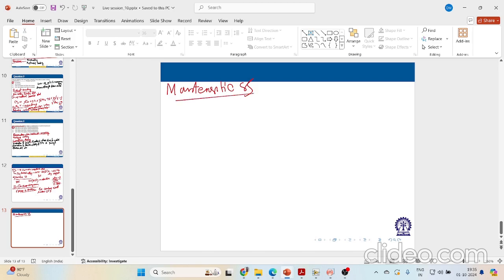Now, martensitic stainless steel can be said to behave like iron chromium alloys containing less than 12% chromium. If it is containing less than 12% chromium inside the gamma loop, then we can say that the characteristics are somewhat similar to martensitic stainless steel, right?